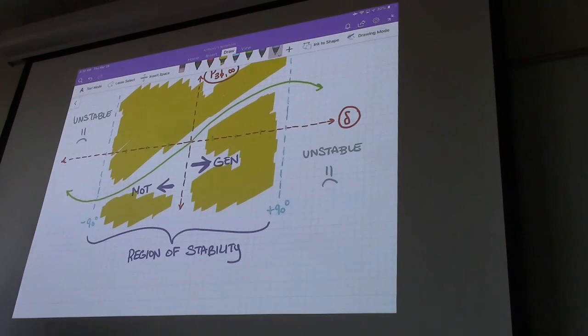So, in a physical system, you're not going to see too many times where phase differences between adjacent buses are going to reach anything more than a couple of degrees. Okay, you're not going to see 50-degree differences between the two. If you see a 50-degree difference, 99% of the time that already indicates you're well into an instability and things have essentially crashed. You're not going to be able to recover without restarting the system.